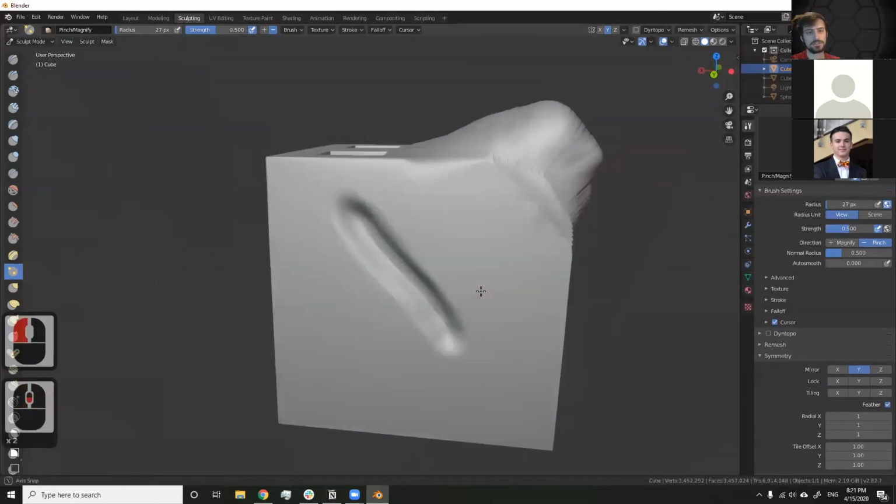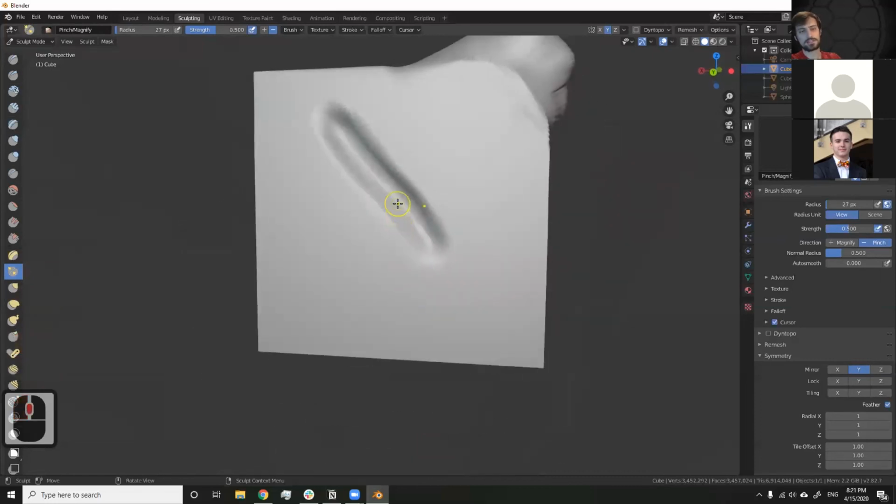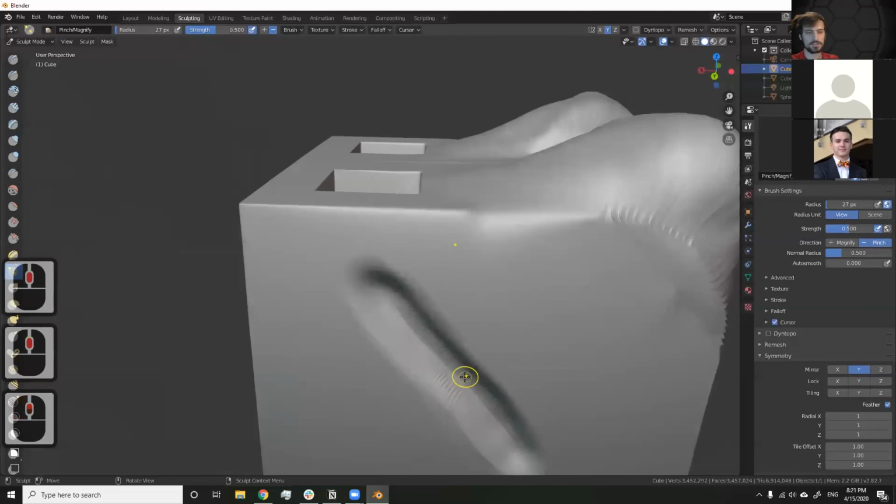So this allows you to make more rigid edges onto a sculpt that might be otherwise a little bit more freeform. So if you're trying to model something that has hard edges in it, say something like an insect that has a hard shell, or a crab, where you have organic shapes but still hard edges, it can be a really nice combination to do a crease to get your initial divot, and then use the pinch option to really sharpen up those edges that you've added on.